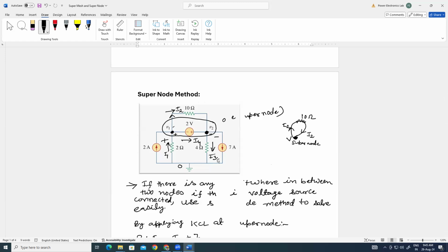No sir, by the diagram we are saying that V1 minus V2 should be 2 volts. If there would be I4, then it would be something else. How could it be 2 volts if some current is going through that? In between V1 and V2, only this voltage source is there. There would be no drop for this I4.